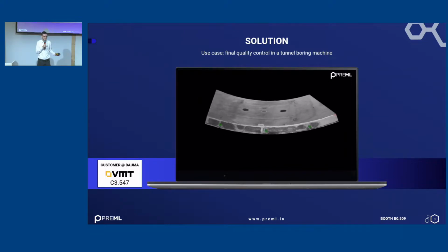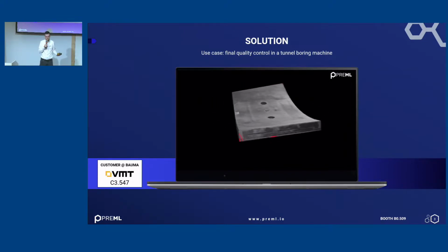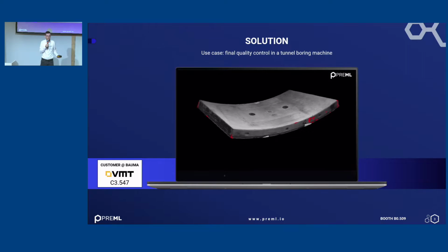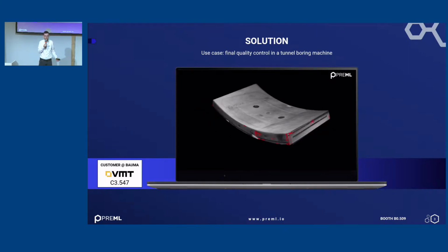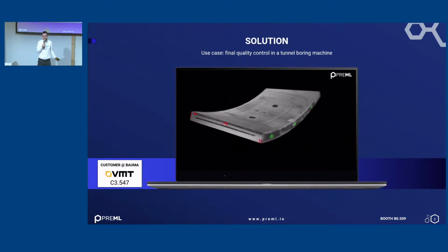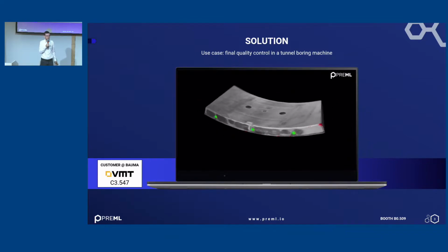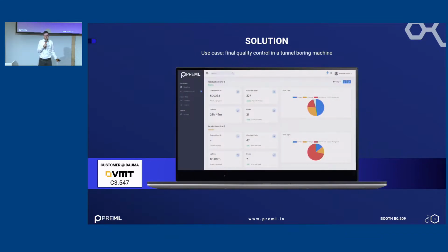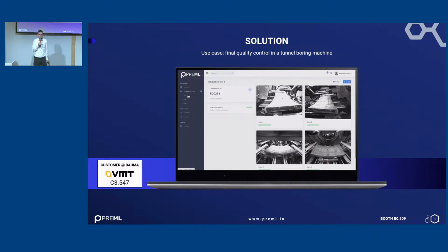We use artificial intelligence for that, which is trained to, for example, detect cracks in the surface of the concrete element, or if the dowels or other built-in parts are missing or hanging away. All this data goes into a database, and later on the machine operator gets a notification as soon as we find something, and can then do the corresponding action.